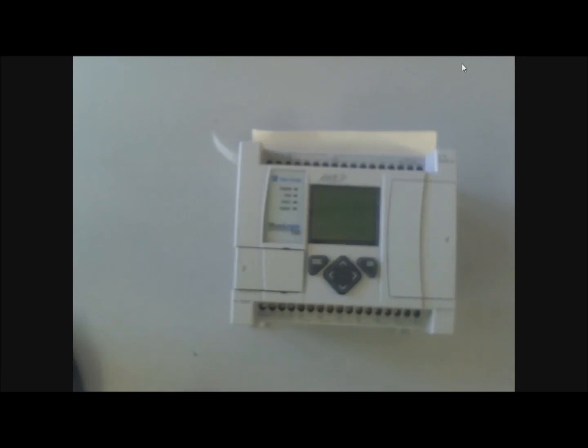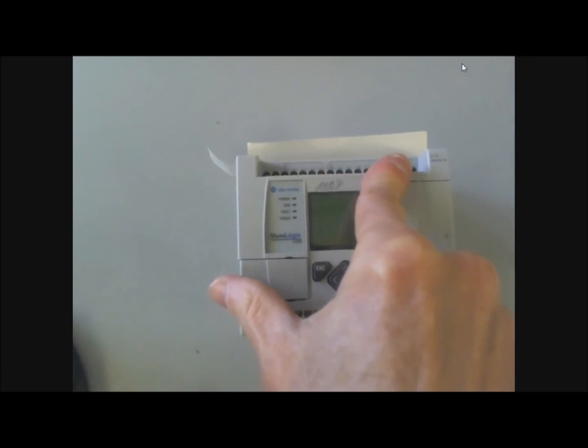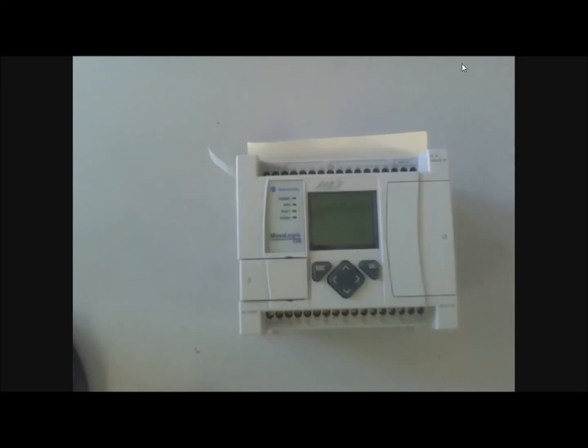Now, inside the PLC, the symbols we just use are normally open contacts and normally closed contacts. We use the relay coils, and then we use a bunch of rectangles to represent timers, counters, and all that other kind of stuff. On the outside, when you draw the diagram for this, you have to use the symbols for the electrical control devices, right? You understand? So that's where all those symbols right here come into play.